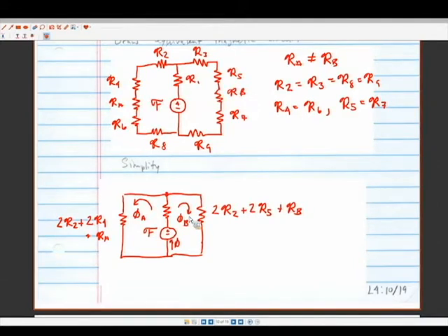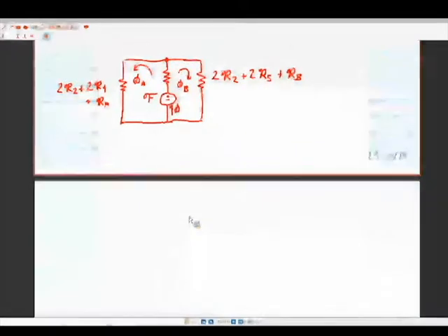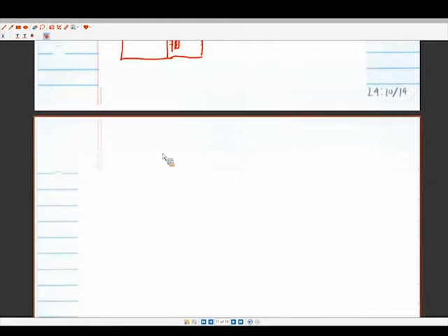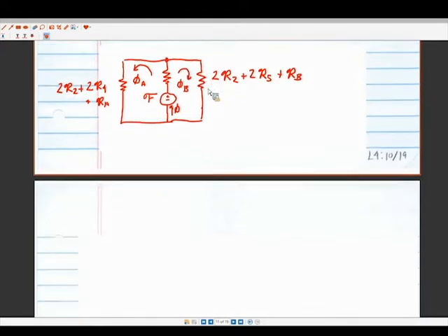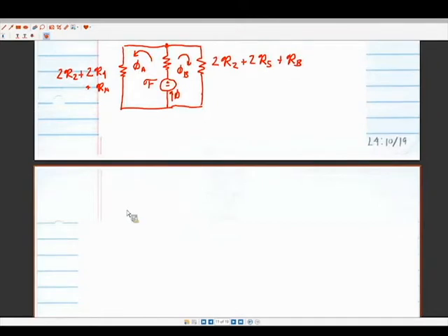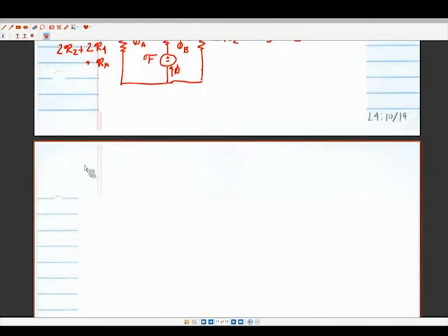Okay, so just as an aside here, well, we won't get to that yet. This is a current divider. We're going to use then the form of what is the entire reluctance of the circuit. So first we're going to combine parallel reluctances on the left-hand side and the right-hand side. Just like the previous example, that's just the product of those two reluctances over the sum. Same idea here. So I'm converting this circuit, which has 3 branches, into one that just has a single loop.